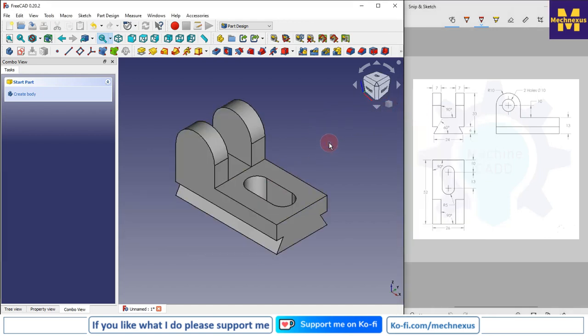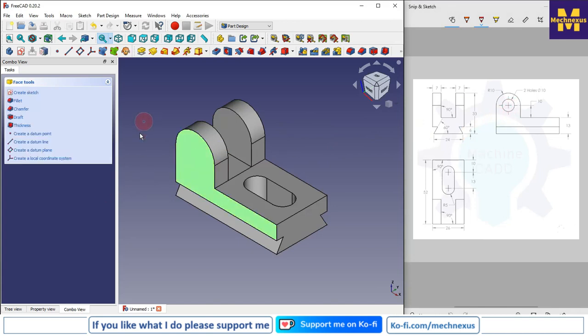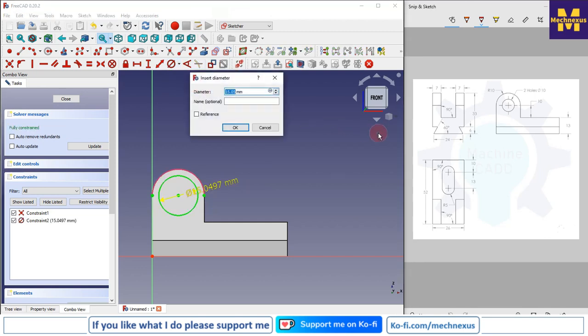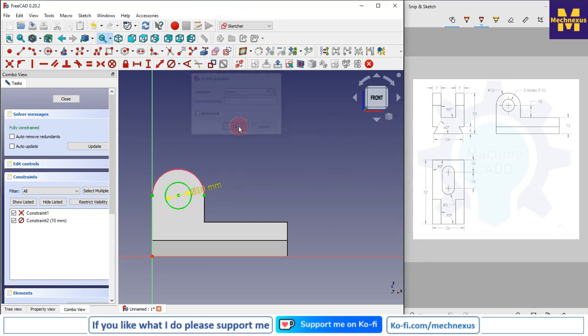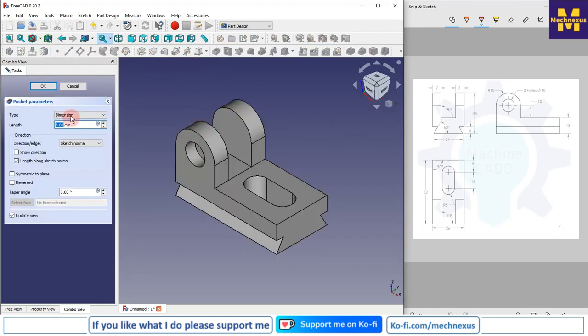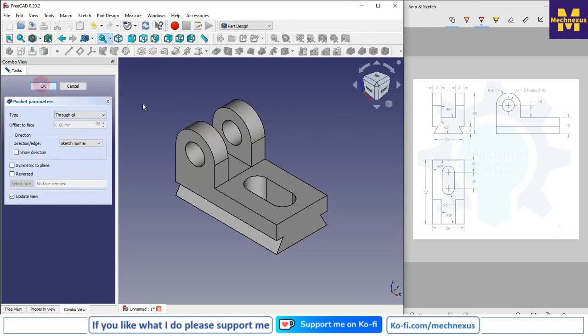So now we will make this hole. So for this I will select this face, and as it is a very simple hole, we are not going to use the hole feature. So I will simply say sketch, and I will convert this outer arc, and I will simply draw a circle, and I will give it a diameter of 10, and I will say OK, and I will say cut, and I will say through all, and I will say OK.